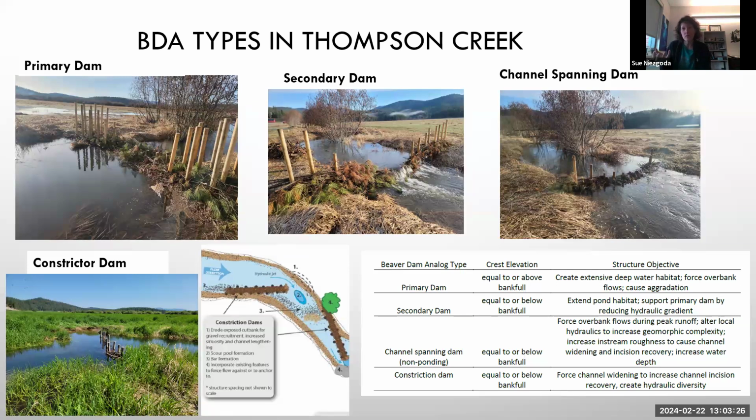They also use those in stage 0 restoration design for full channel floodplain reconnection. But anyway, it helped highlight areas where there used to be an old side channel. And so we would put a constrictor dam in a location that would kick that flow out into that relic side channel.